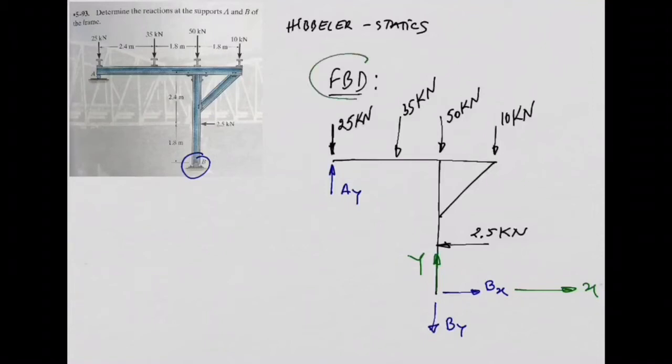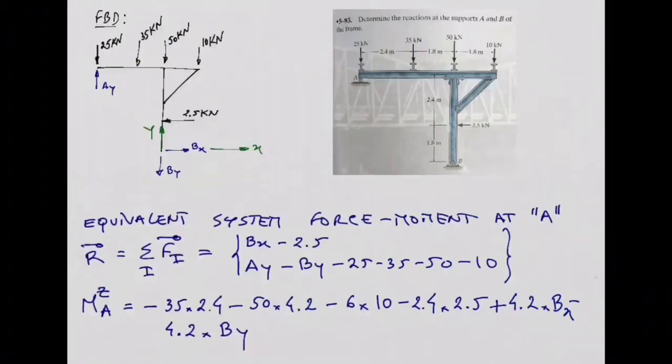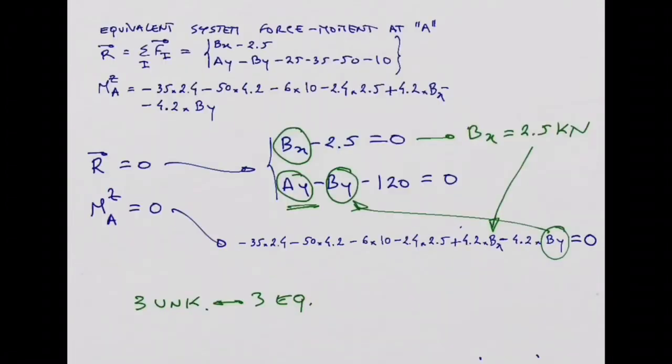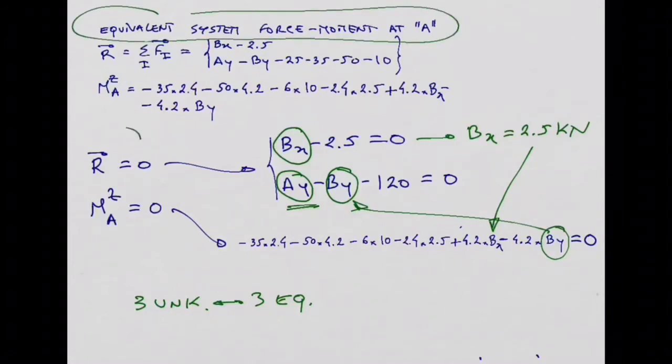In my opinion, the free body diagram is the most important thing when you solve this kind of problem. Once you have the free body diagram with all the forces included, you just need to build an equivalent system, force and moment, and then write the equilibrium equations. That's it. Always like this, okay?